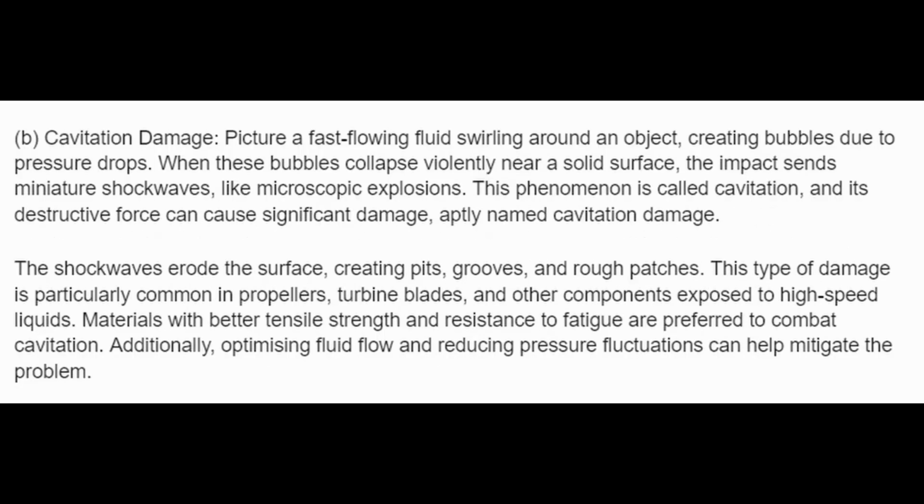B. Cavitation damage. Picture a fast-flowing fluid swirling around an object, creating bubbles due to pressure drops. When these bubbles collapse violently near a solid surface, the impact sends miniature shock waves like microscopic explosions. This phenomenon is called cavitation, and its destructive force can cause significant damage, aptly named cavitational damage. The shock waves erode the surface, creating pits, grooves, and rough patches.